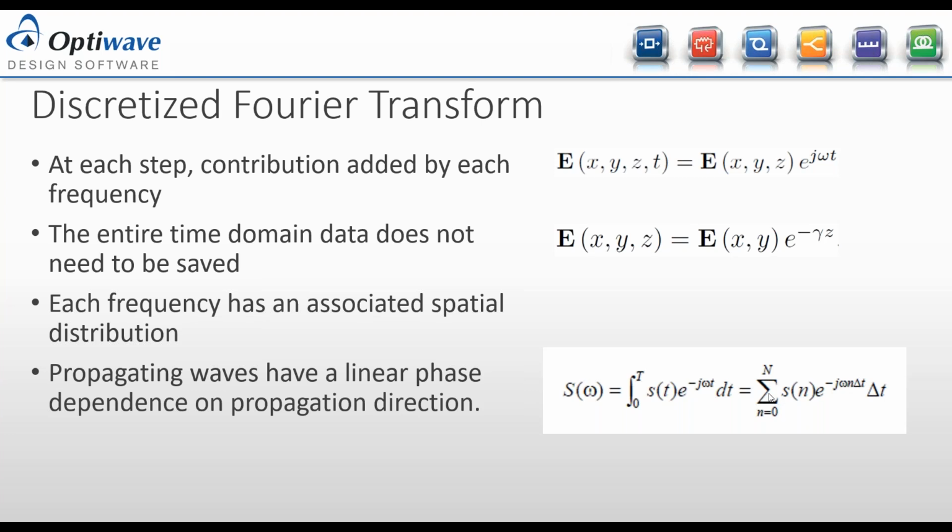It's like a running calculation. Obviously, we do it for multiple frequencies, right? Since we're usually exciting it with a pulse, we can do it at multiple frequencies. You can set that up again at the beginning of a simulation. And then the observation object will be showing each frequency's spatial distribution. Or if you had set up the simulation to be in the frequency domain, what that final state of the domain is going to look like at a certain frequency.